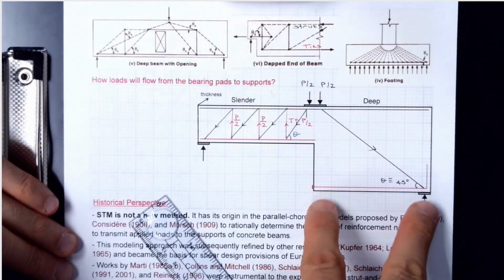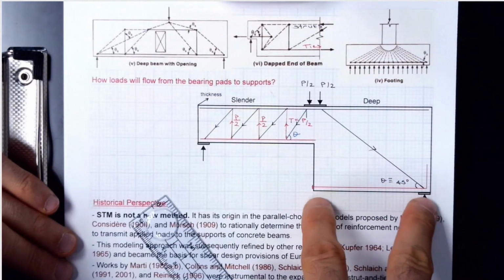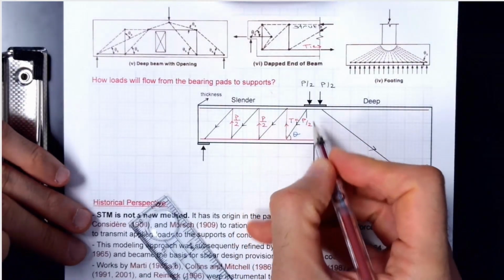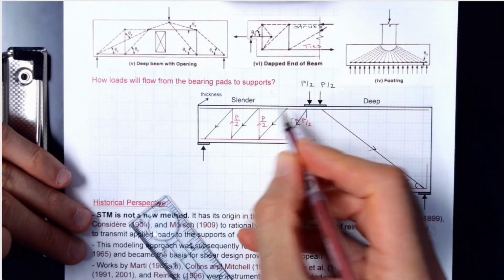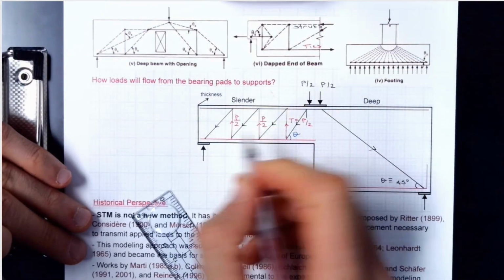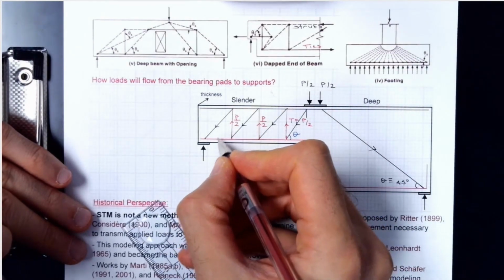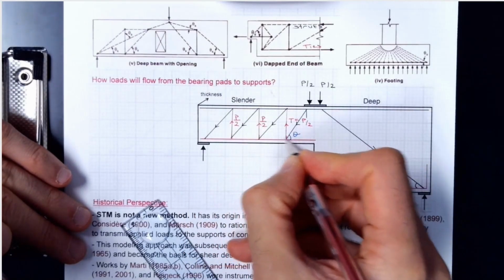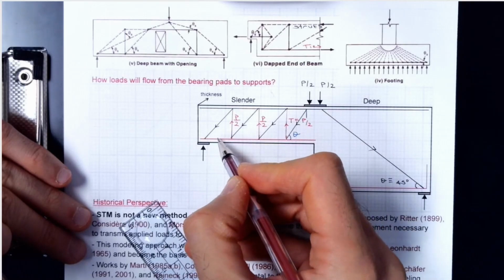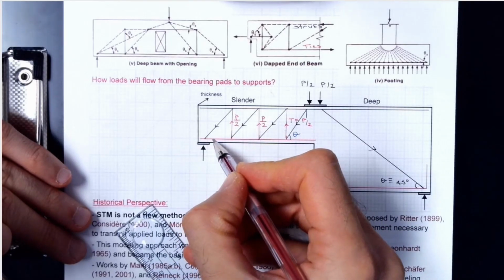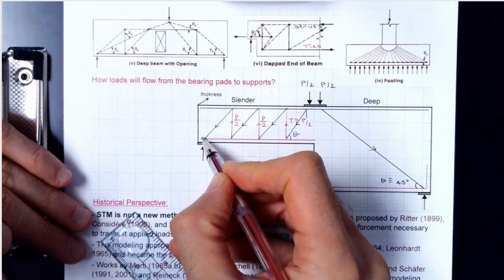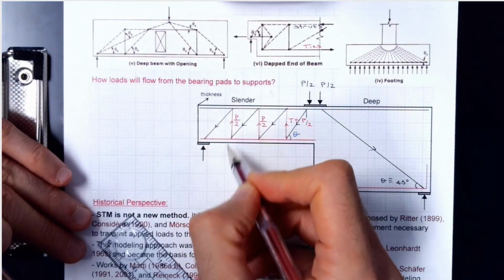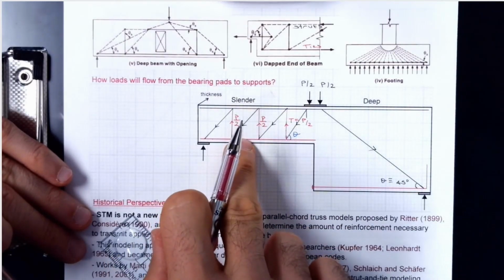Okay. The anchorage, I wanted to highlight the anchorage. If you look at tensions for the system, the tension in the tie will keep diminishing. If you do this analysis, the tension would be maximum in the midspan region, but the tension would diminish as you come closer to the support. So typically you can cut the rebar at the support because tension would be minimal. So that's the slender element behavior.